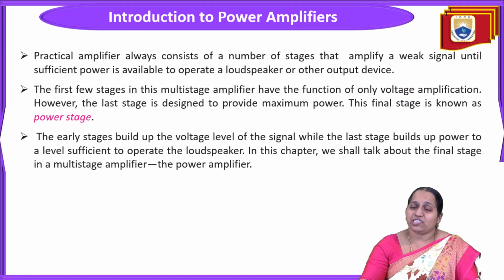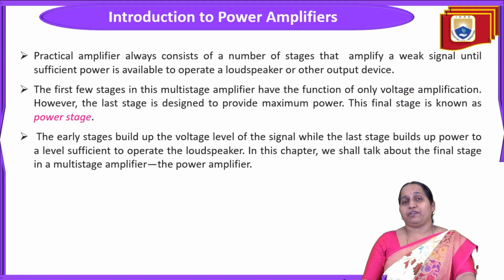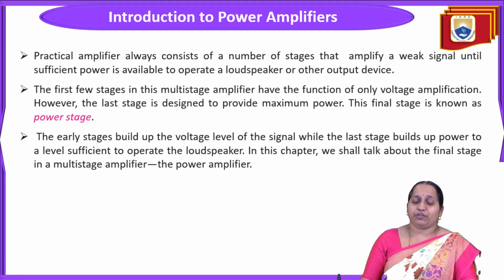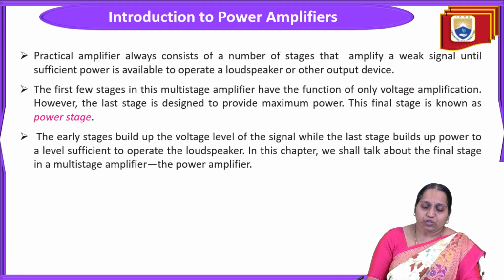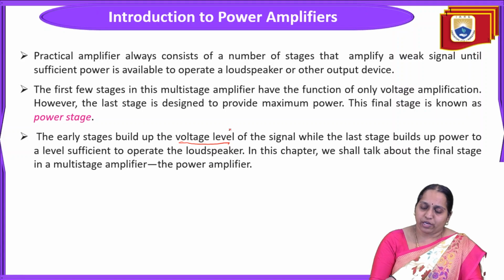But the last stage is generally designed to provide maximum power. That is, power amplification is done in the last stage only. So we call the final stage of a multi-stage amplifier the power stage. That is the reason why it is called the power stage. Early stages build up the voltage level, so early stages are mainly used to amplify the voltage level of the signal.